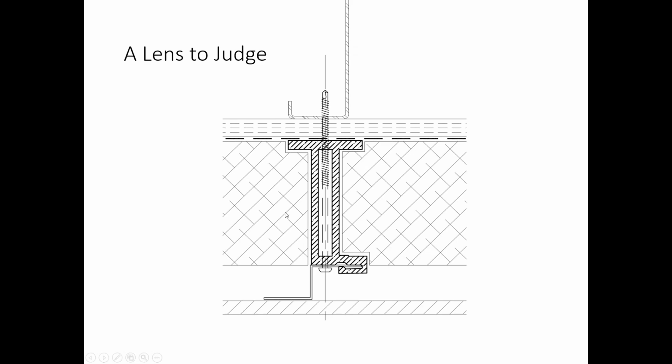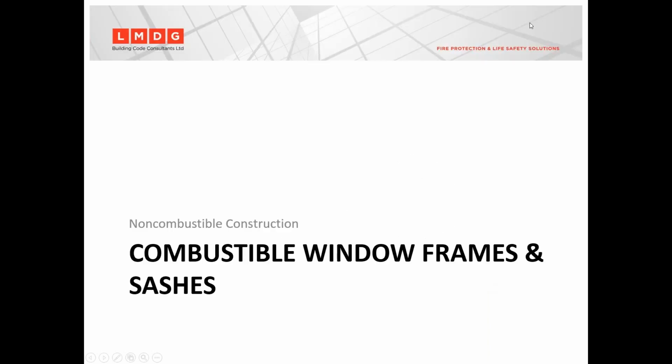If, on the other hand, this cladding was attached to metal on the outside, but then there was just composite through to the inside and a separate fastener, that would mean that that composite is the only thing holding your cladding on in a fire. And that may be fine, but I haven't seen a lot of extensive testing on that point. Whereas if you see the direct metal connection, that's fire safe by observation. We just have to realize that we want as little metal as possible, because the more metal that makes that direct connection, the more thermal bridging comes and the less energy performance we get.